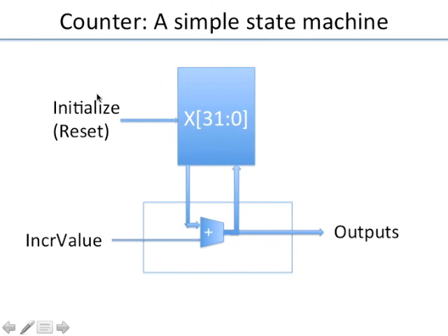One important thing to notice out here is this portion, initialize or reset. It's always important to be able to set the initial state of the state machine. Otherwise you can end up not knowing where it's starting. Sometimes it's okay, but most of the time, as a safe design practice, you always want to have a way by which you can set the state of the state machine, overriding what the computation block is doing. So it's just a good design practice.